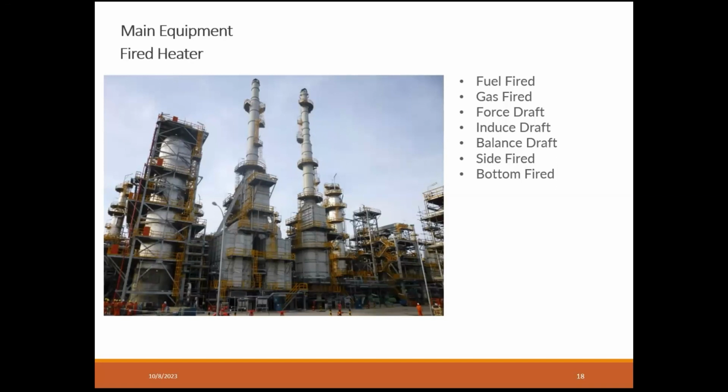Global scenario means that if the plant is tripped, for instance due to power failure, definitely the whole plant will trip, and there will be a lot of relief valves being operated, and all these gases will be routed to flare. It is important for the flare to be designed to cater for the global scenario.